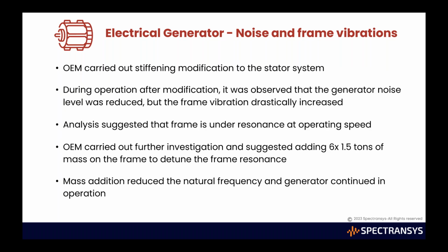So then the OEM, based on this analysis, carried out a stiffening modification to the stator system. If you have seen any generator, there will be manholes on either side to gain entry. Normally they are located at the center of the generator frame, so you have access only to the center of the frame. So the modification was done only at the center of the generator.